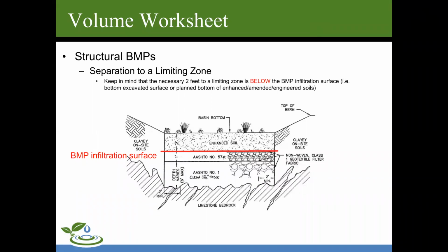When designing infiltration BMPs, keep in mind that the necessary 2 feet of separation to a limiting zone is measured from the bottom of the excavated surface or planned bottom of the enhanced, amended, or engineered soils.